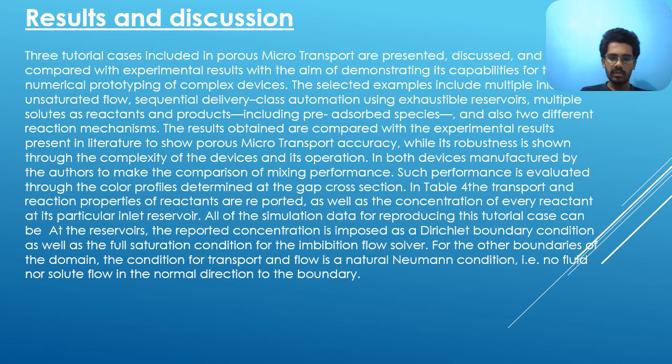The reported concentration is imposed as a Dirichlet boundary condition, as well as the full saturation condition for the Richards flow solver. For the other boundaries of the domain, the condition for transport and flow is a natural Neumann condition, either on fluid or solute flux in the normal direction to the boundary.